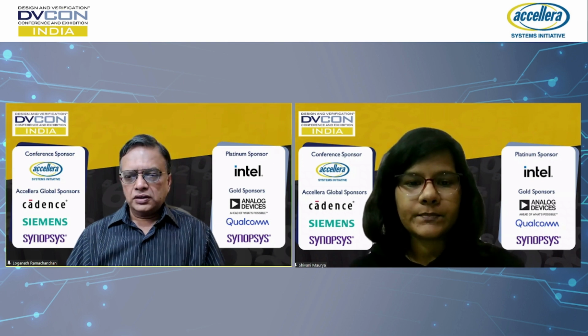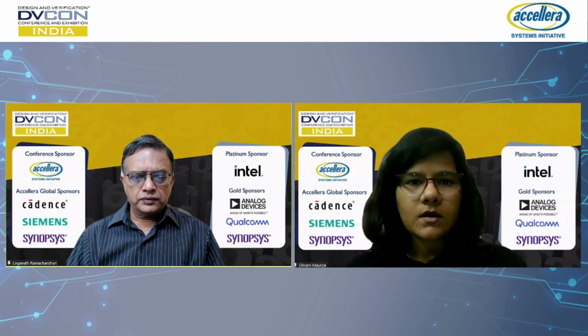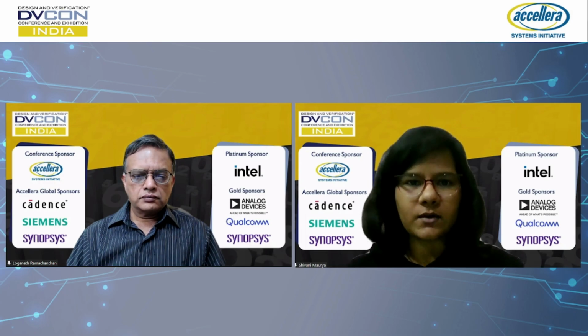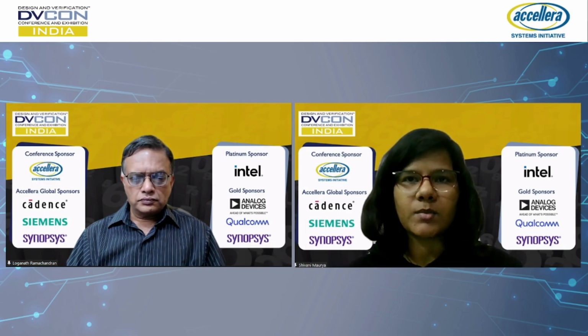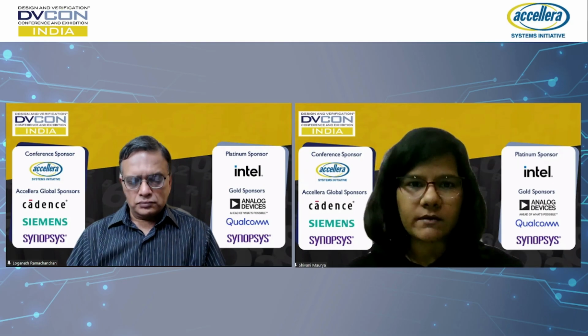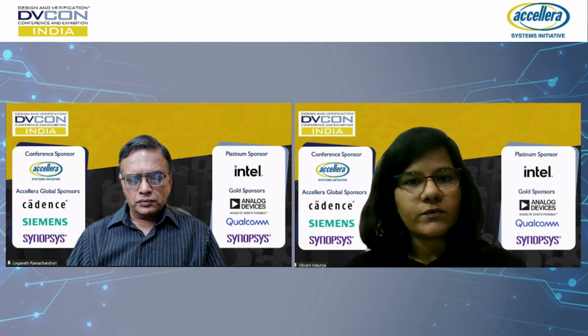And one last question. Was there any modeling guidelines followed for the bond wires or interconnects for the 3D structures? No. This is purely digital time domain modeling of the effect. So we did not come up with any capacitive or inductive modeling as of now in our channel model, but it can be done, because at the end of the day, it is all UVM compliant.